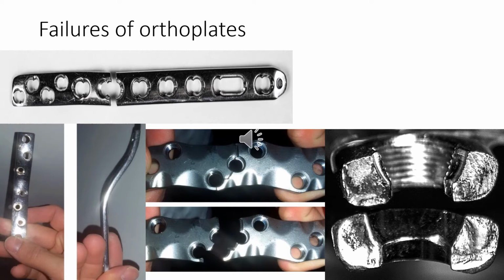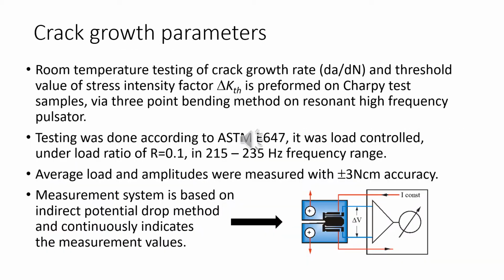To start with, before we apply numerical methods, of course, we need to know some parameters, and that will be accomplished through standard testing, as you will see in the next two slides. Basic data about testing is shown in this slide. It was done according to ASTM standard E647. It was done in load control and under load ratio of 0.1